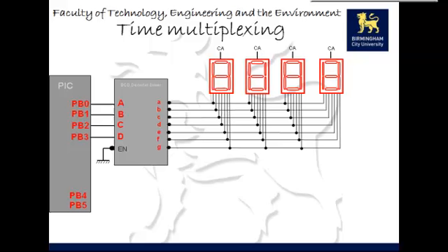Unfortunately, we just have not got enough current to illuminate all 4 7-segment displays. To try to illuminate all of them would mean that not even one of them would appear to be on, because there's just not enough current to illuminate the segments. What we can utilize here is the common anode feature of the 7-segment displays, and treat that as a chip enable.